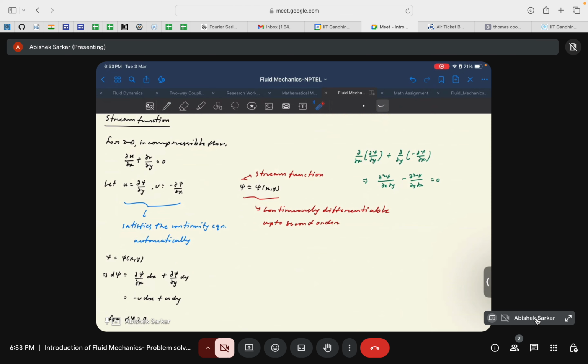That's why I don't want to explicitly say it's only defined for incompressible flows, but the very gist of it is that it is defined in a way so that the incompressibility condition is satisfied, which is that mass conservation is satisfied. Okay, but still there might be scenarios where it can be changed. So I will say it's a conditional case. But if not explicitly mentioned, then you can say these two terms, that is 2D incompressible flows, are required for defining stream functions.